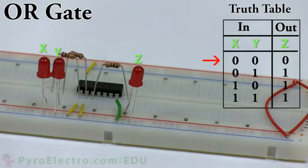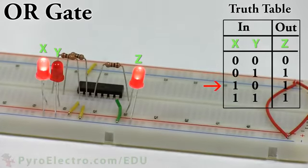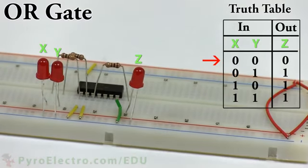When the input is 0, 0, represented by the LEDs on the left side, the output is 0. When we change the input to 0, 1, the output is logic 1. Changing the input to 1, 0, the output is still logic 1. And finally, we test when the input is 1, 1, and you can see the output is also a logic 1, represented by the LED being on. Thus, the OR gate follows the theory exactly.